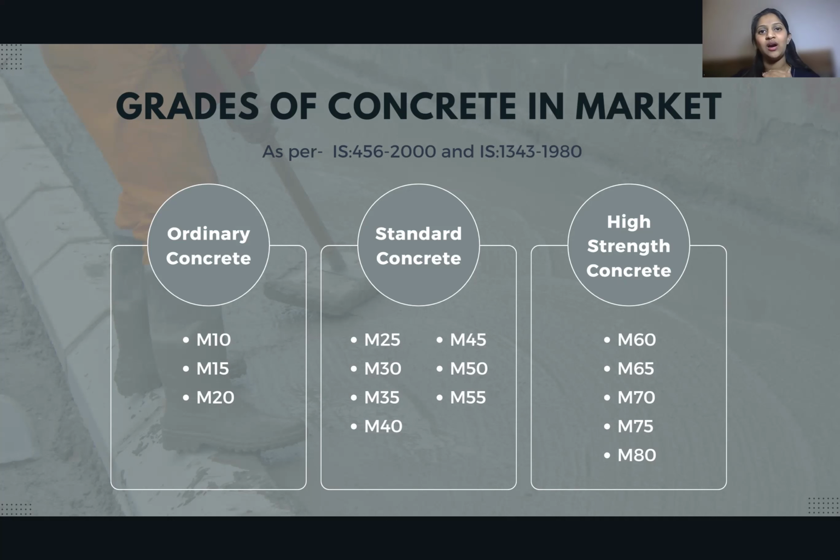This way, high strength concretes will be used in infrastructural projects because there is a lot of live load. There is a humongous amount of load that will be passing through these structures. Even in high-rise buildings, for the foundation, just in case a pile foundation is required, all of these high-strength concretes are used.